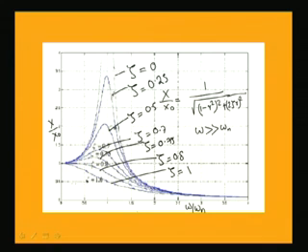And you can observe that for a value more than 0.75, the magnification factor is less than 1. So, you can observe that with an increase in damping, the response of the system decreases, and also you can observe the maximum peak is occurring towards the left of the value omega equal to omega n.